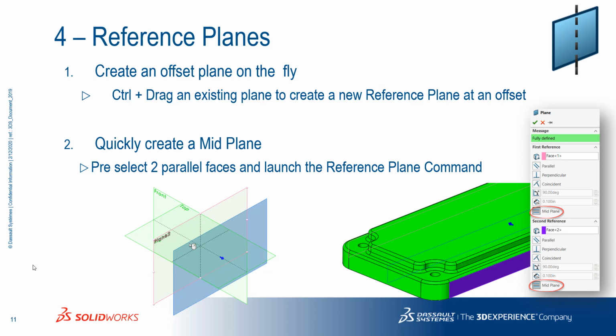Reference planes. The tip is not that reference planes exist. The tip is two ways that you guys can quickly add reference planes. One, on the fly. That's my favorite way to add reference planes. My second favorite way is to add a mid-plane very quickly. So let's take a look at this.